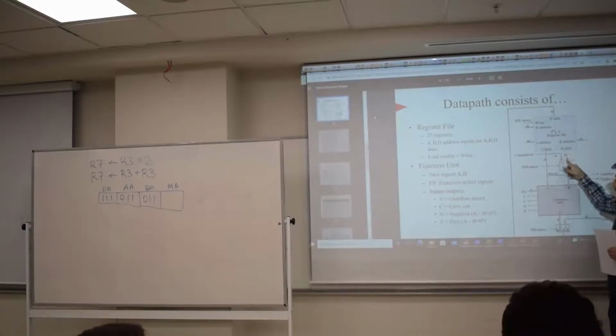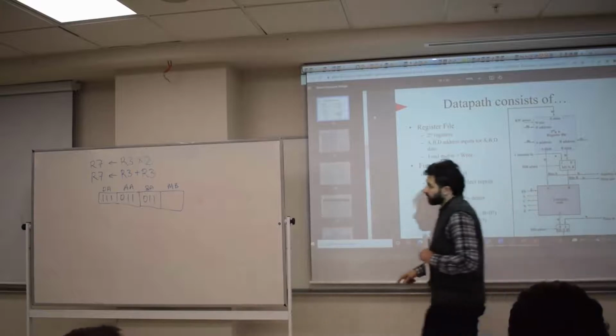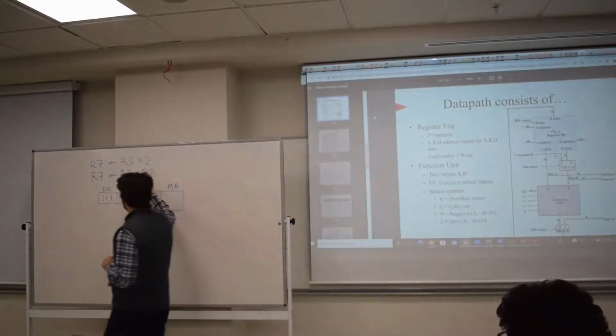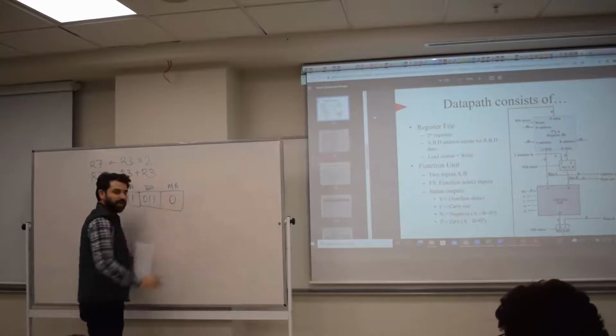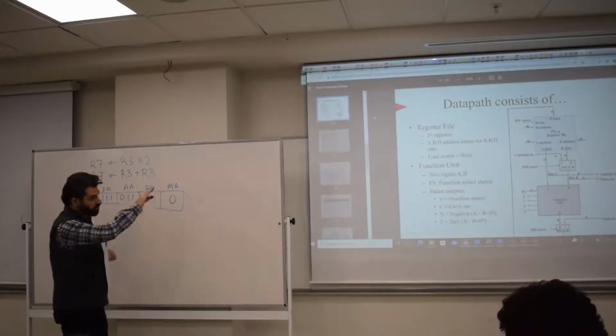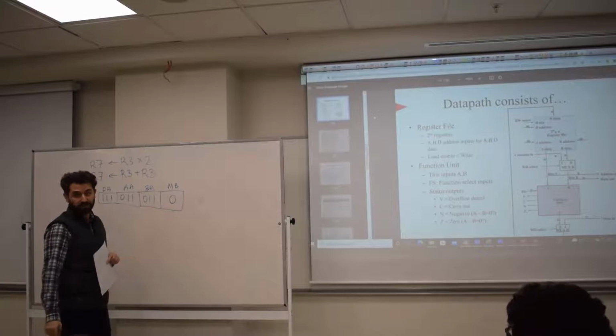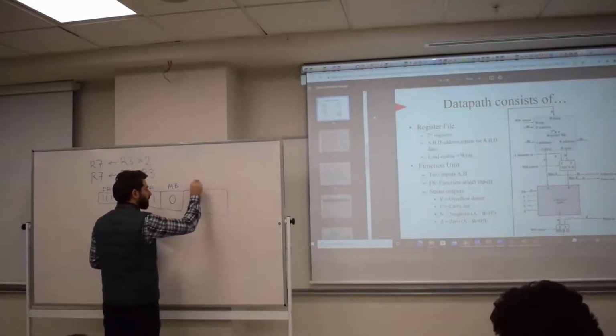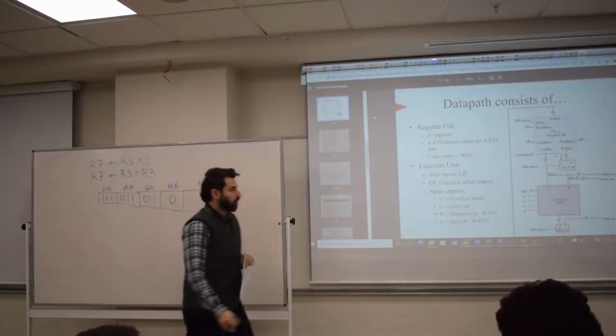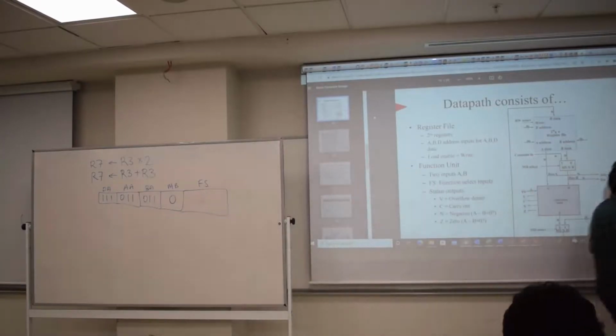In this case, we're getting this from the register file, right? Because it's R3, right? That's B, that's A. So therefore, I have to choose one bit, 0, so that the corresponding input-output relationship is satisfied. Next is FS, which is 4 bits, as you know. So I look at the table again.